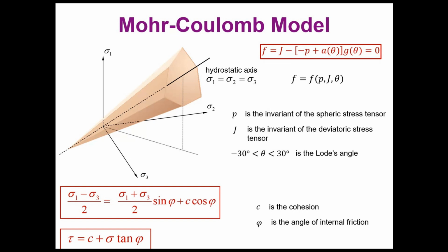And as you see, the definition of this surface is not only dependent on the deviatoric stress, so it's not only depending on failure by distortion, it's also taking into consideration the failure of load that produces hydrostatic states of stress, because there is a limit. There is a limit in here where you are approximating to this, and this area is usually the tensile area, so it's the smaller one.